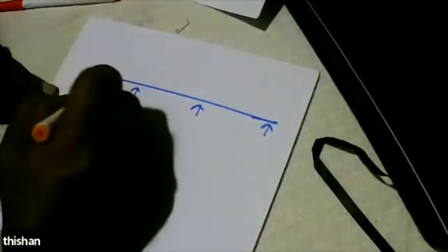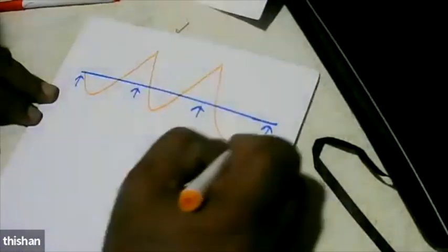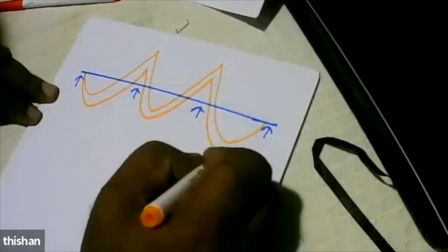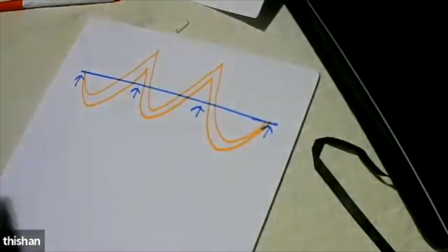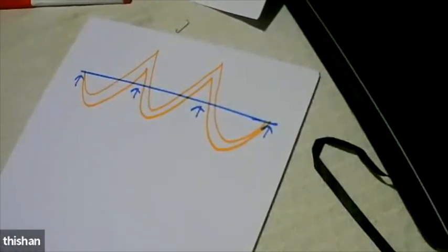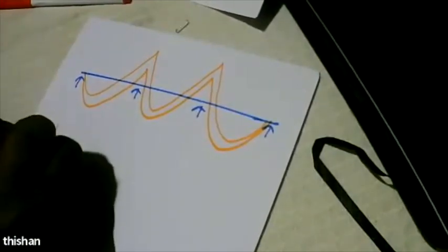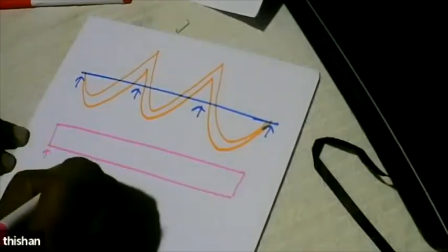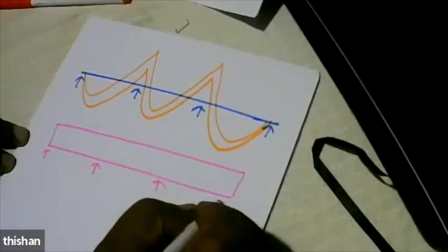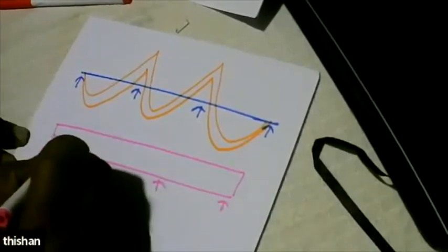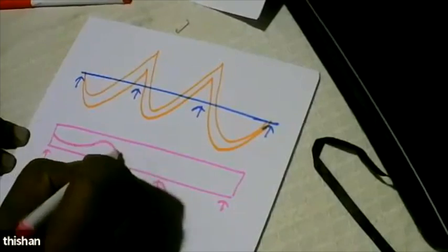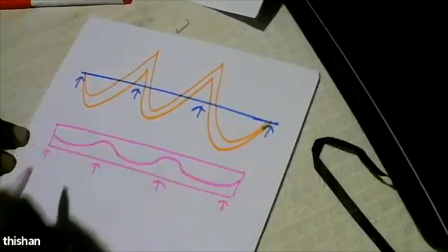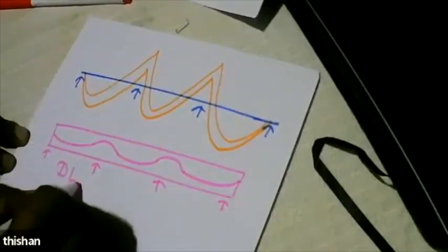So we're going to have large hogging moments, right? But again, we have to be practical. Why? We know that when we fix the cable, what is the moment we have? Now, we don't have the vehicles on the beam. What do we have? We have only the dead load or the self-weight.